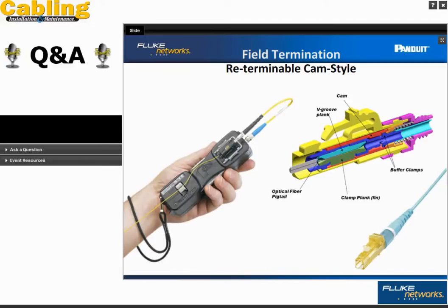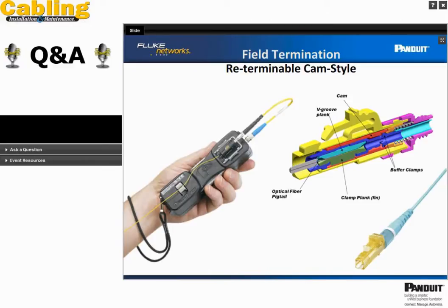The one that I showed in the example would have an extremely low connector loss, and the other would be extremely high. It's really the higher speed links. If you're doing Fibre Channel 8 gig and above, or 10 gig Ethernet and above, these are the requirements at the component level that would maintain application standard compliance.